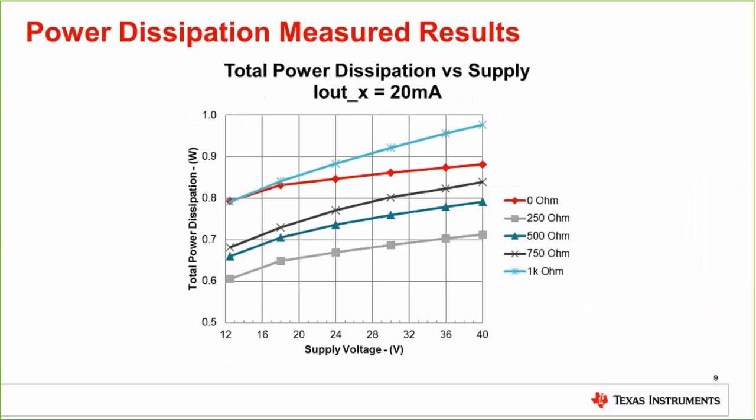So the primary goal that we wanted to hit was this power dissipation, and again, this is the cumulative effect of the DAC8775 along with the LM5166. Across 10 PC boards, what's plotted here is the worst case for each of these loading conditions. So the worst case ends up being this 1 kilo ohm load condition, followed very closely by the 0 ohm load condition. But you can see that for all cases, the design is below our targeted 1 watt power dissipation goal.